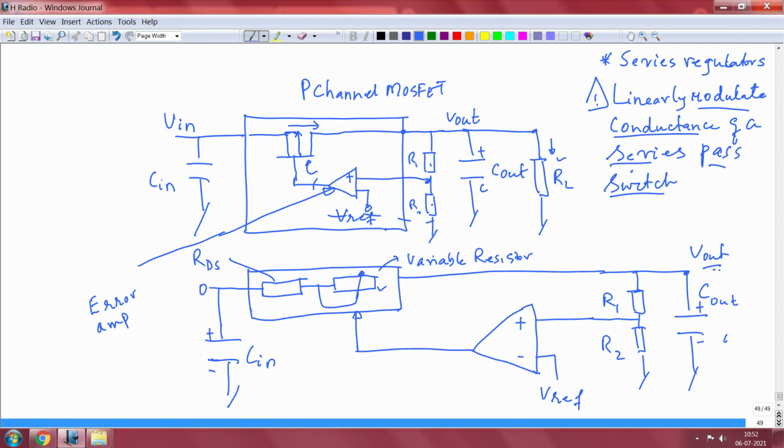That is all that is there in a low dropout regulator. RDS on has gone to extremely low values, so dissipation across the MOSFETs has come down drastically, and that is one part. Second part is because there is a very small R value, the difference between the source and the drain has also shrunk.